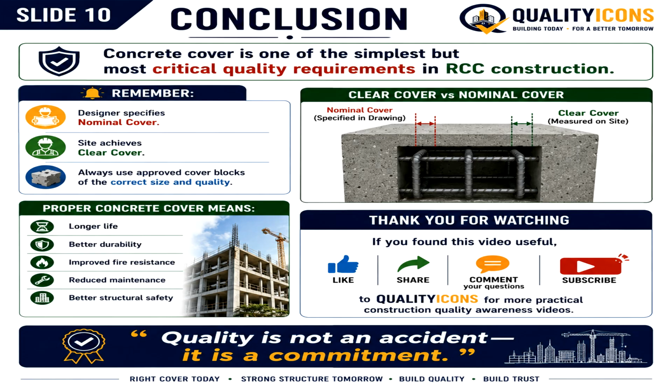Remember these three golden rules. Designer specifies nominal cover. Site achieves clear cover. QAQC engineer verifies clear cover before concreting. Always use approved cover blocks of the correct size and quality.